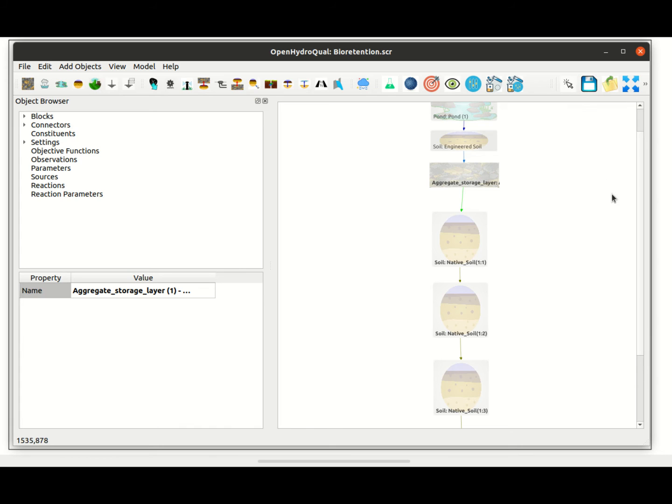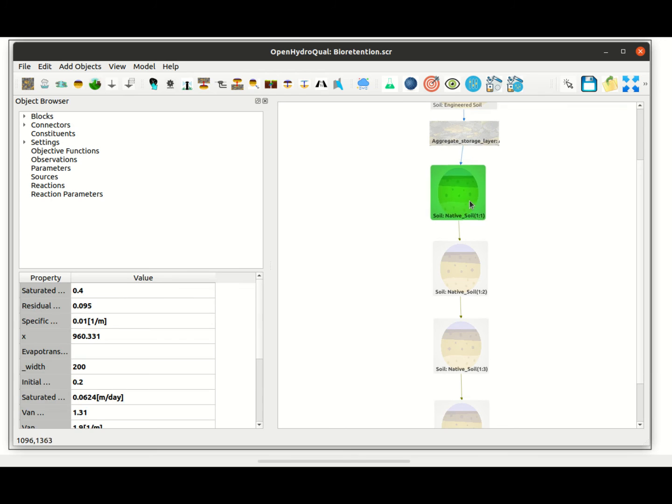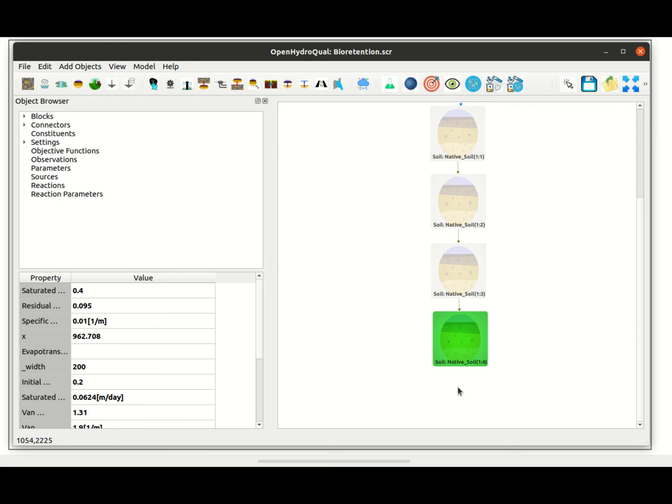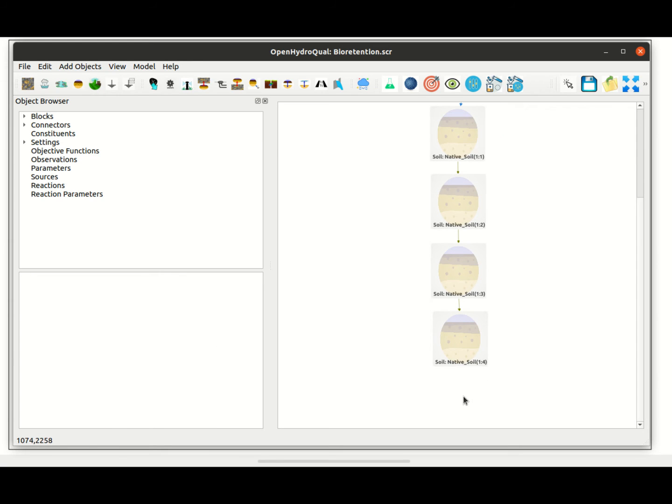And that's it. So one thing is left, and that is to impose our bottom boundary condition. For the bottom boundary condition, I can actually place a groundwater, but the problem is if I place a groundwater, the groundwater can fill up, and the pressure can build up as water enters the groundwater block, unless its capacity is sort of infinity. So instead of having an infinitely large groundwater block, I will use a fixed head boundary.